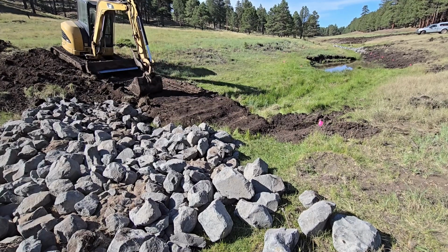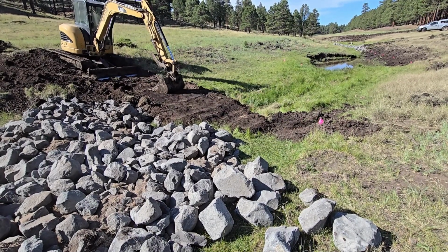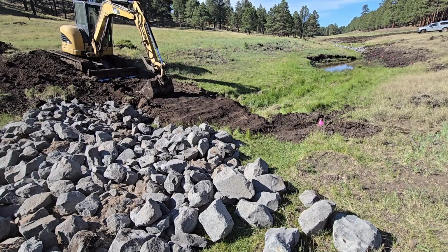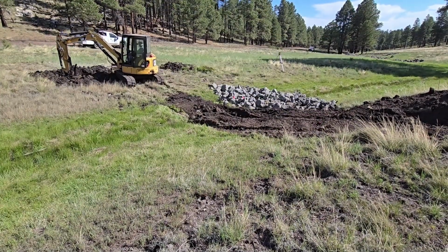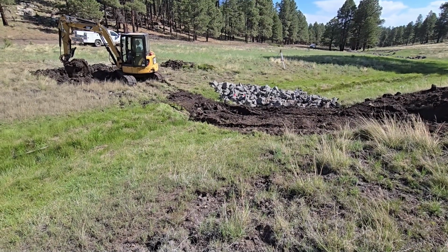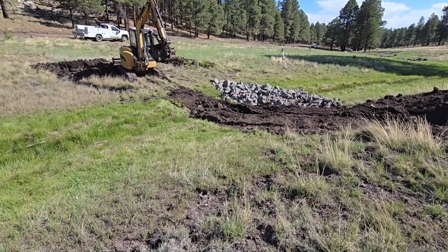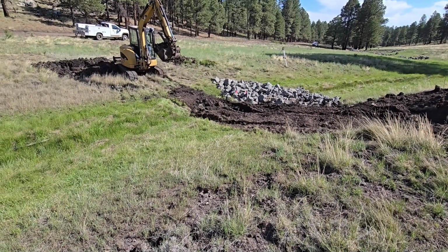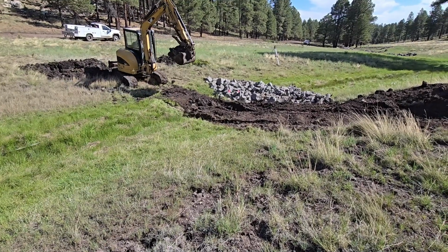Building a groundwater dam is the most effective and lowest cost way to restore water in a dry wetland, especially in an arid region. Here Don has dug a borrow pit to come up with enough clay to fill the core trench that's needed to build the groundwater dam. There are 2 reasons why he needed more soil. The first is that the permeable soil he removed contained gravel, rock, and sand. We don't want to place this permeable soil back in the core trench.